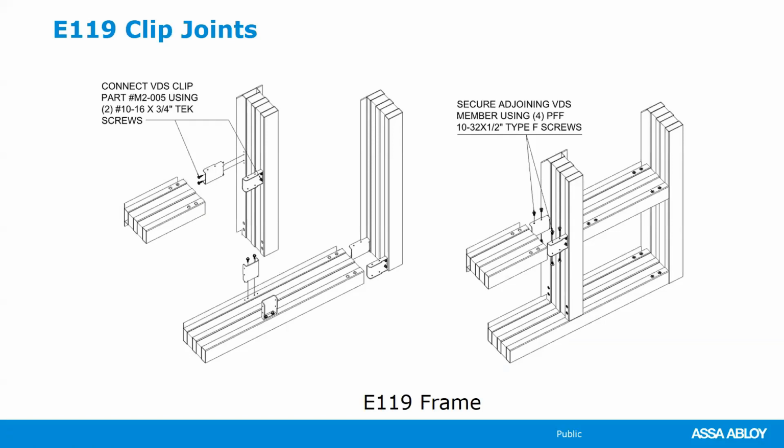Looking at how these frames are held together, you can have multiple glass panels using a clip joint, as it's called, and the entirety of the machining that's required to assemble it is done prior to the material being received either at the distributors or at a job site. The material in the frame is machined out, and the holes to accept the fasteners for the clips are also included.